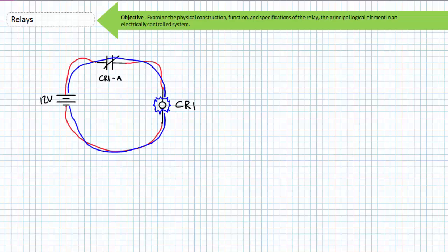However, I really get a kick out of this particular activity because it directly highlights the relationship between and the function of a relay's coil and their associated contacts. You'll notice 2 important points about this activity. 1, the repeated opening and closing of the relay is occurring at a natural frequency, implying there is only so fast a device composed of moving parts can move. We'll learn in later lectures about solid-state relays, relays with no moving parts that can rapidly turn on and off at high frequencies, not limited by the physics of moving objects.